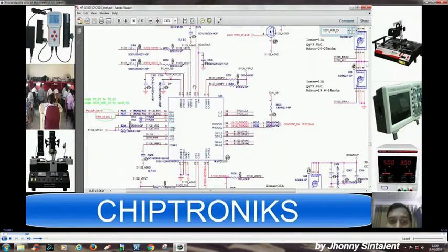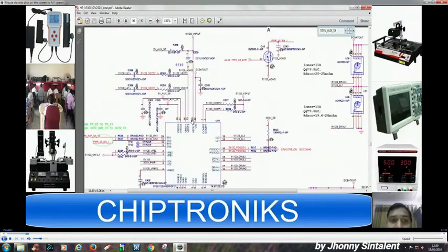Then in that case what do we have to check? We have to check Vin, that is DC bat out. If this IC is having Vin and this LDO is not coming, then what can be the problem? The problem would be in the IC itself, right?